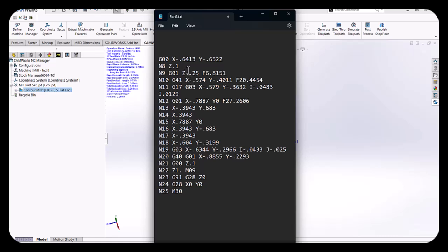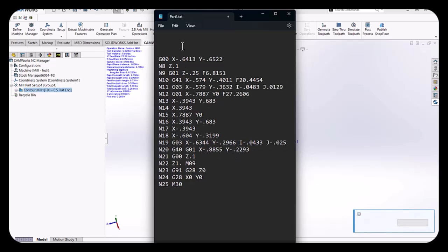So that's going to be put into our tool offset data and is not going to be part of the program. However, we do need a G17 plane, which is the XY plane. A lathe will default to G18, so we definitely need to tell it this, but we cannot tell it to go to G17 inside of the G12.1 information. So we're going to get rid of it here, and we're going to place it up before we go into the G12.1.